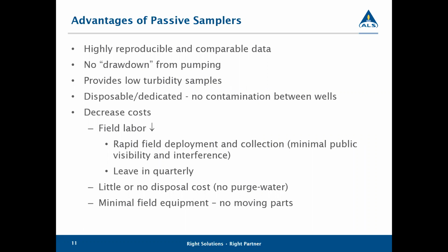The passive samplers are disposable, they're dedicated, so they are one-time use. You deploy them, you collect your sample, and then you deploy a new one for your next sampling event. So you don't have to worry about any contamination between wells. You don't have to worry about decontaminating any field equipment between wells. It's one and done, and you move on.